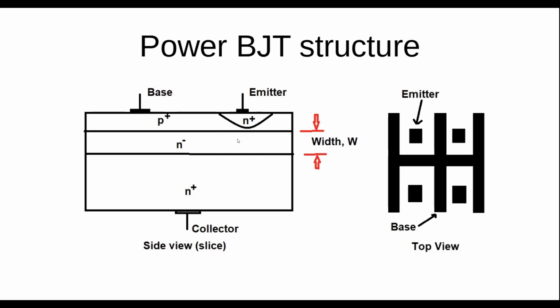Depending on your application, if I want to switch off very quickly, then quasi-saturation is better. But if I really want significantly more current flowing, then I would want to go into hard saturation. That's a way to think about it. It's why, depending on the application, you'll see both of those approaches, and you'll pick one of the two based on what your application is.